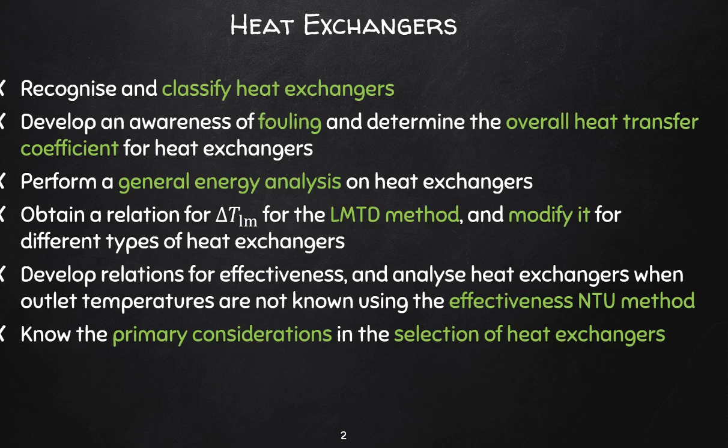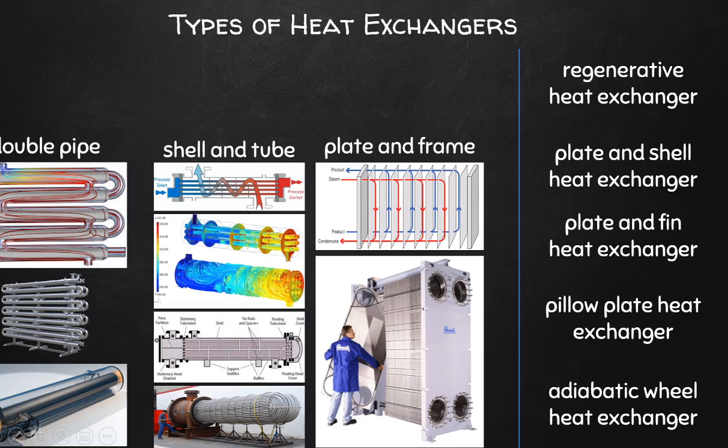Namely, the log mean temperature difference method or the number of transfer units method is what is typically used, and the number of transfer units method also is called the effectiveness NTU method because we use two variables, namely effectiveness and NTU, to do these exchange designs instead.